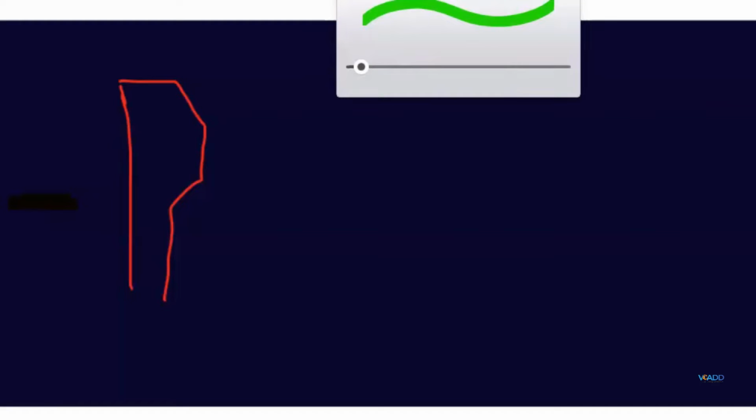So how to consider, just take an example of the snap. Serviceable snap and non-serviceable, permanent snap. So how to design that? The shape of the snap you have to change. Now just think about the serviceable snap. So this is a snap. I'll just draw a rough sketch here. The bottom of the snap is tapered so that it can be easily removed. And on the counterpart, there is a slot here. I'll just show it with a different color here. It's not getting highlighted. I'll just choose a different color. No problem.